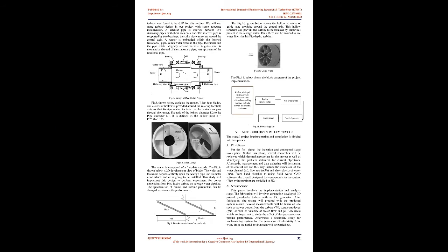The potential of Picohydro is not the same for all areas, as the pressure of these water supply pipelines is different in the different areas, thus potential will also be different. Also, the hydropower depends upon the water flow rate too, so the potential will also depend upon the water flow rate in these water supply pipelines. Therefore, prior to the installation of the Picohydro turbine, the head of water and water flow rate must be considered.